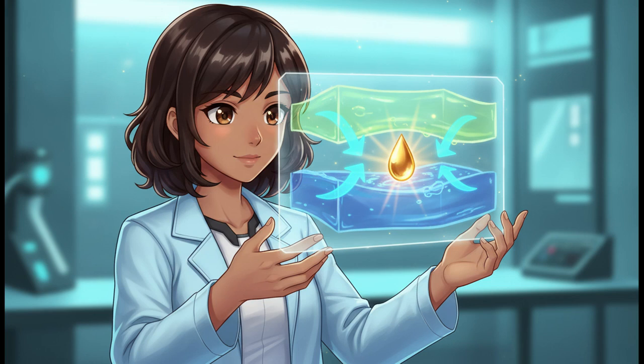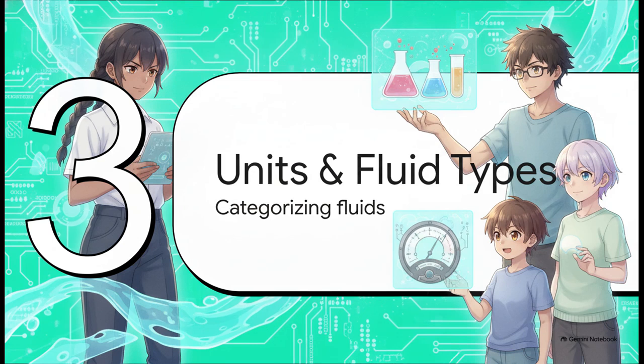And that insight brings us directly to our primary equation for this masterclass. Tau equals mu times dv by dy. Let's meticulously break down those variables. Tau represents the shear stress, and we measure that in newtons per square meter. Our dv by dy, like we just mentioned, is the rate of shear strain measured per second. And that leaves us with mu, our dynamic viscosity. Mu acts as the proportionality constant here. It is literally the mathematical embodiment of a fluid's unique thickness or personality. Okay, let's jump into Section 3, Units and Fluid Types.